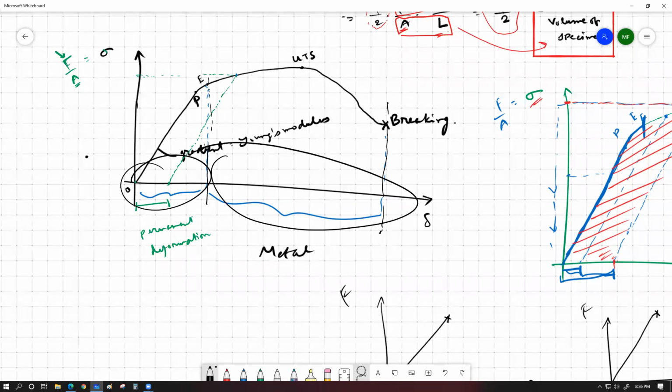So metal is strong, ductile, malleable. Whereas on the other hand, diamond or glass is actually strong, but they are brittle. They don't have any plastic behavior whatsoever. You apply enough force on them, they're going to shatter into pieces. And you can glue them back to the same size, because individual pieces are not going to be permanently deformed.